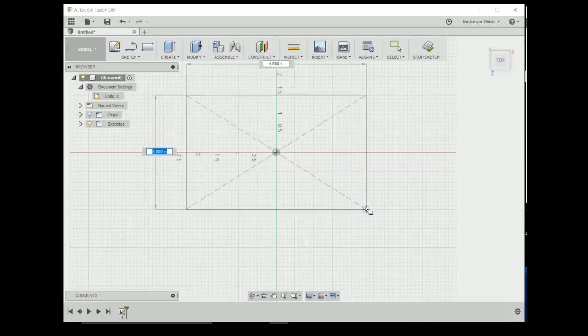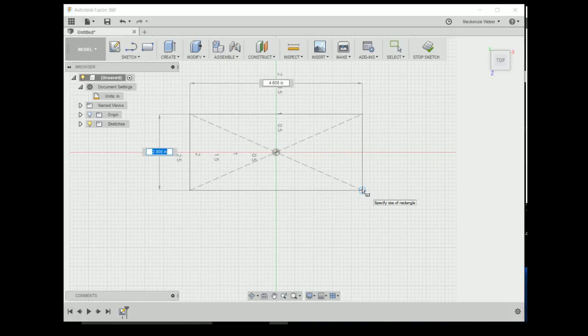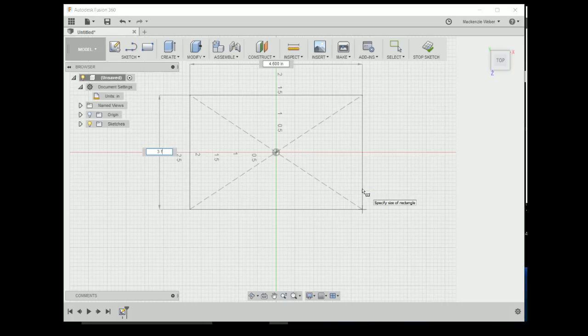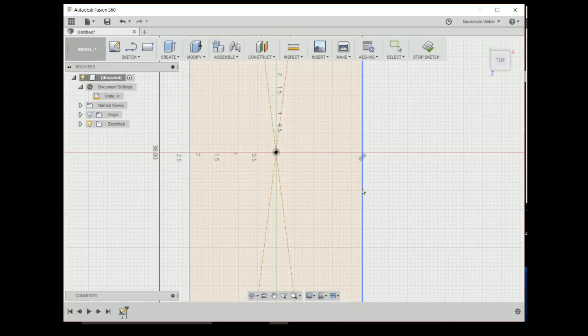And as we click and drag out, some dimensions will appear, and you can set these dimensions. Let's say we wanted to make the table 3 feet by 5 feet. And one thing that's cool is when we're here in this dimension, we're in the inches units, but if we type 3 feet, it will calculate that to 36 inches for you.